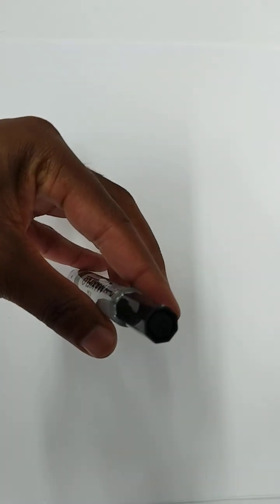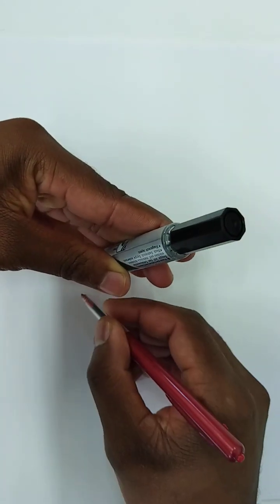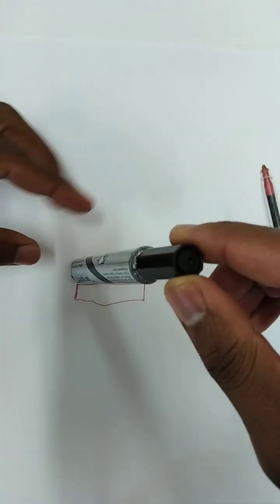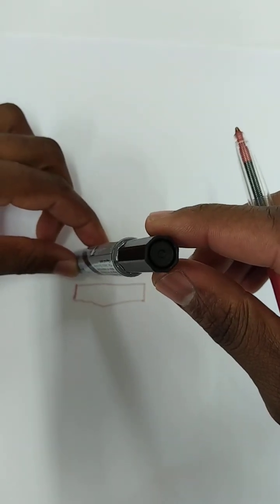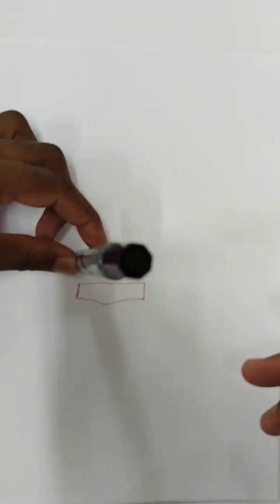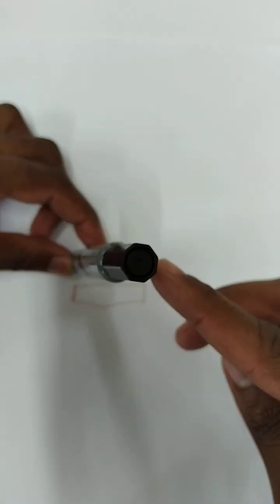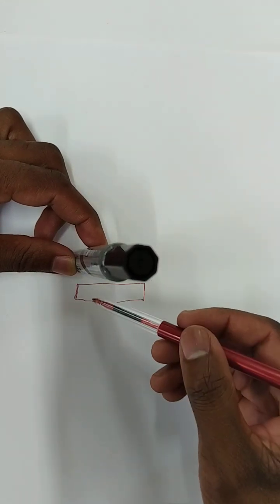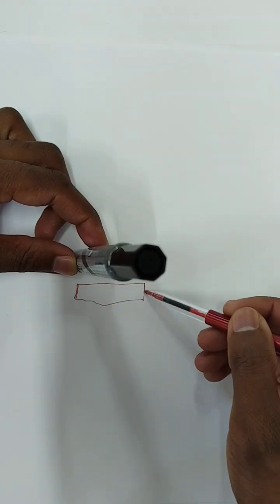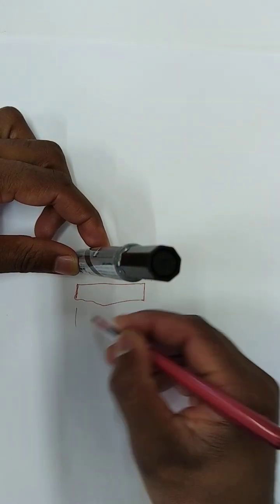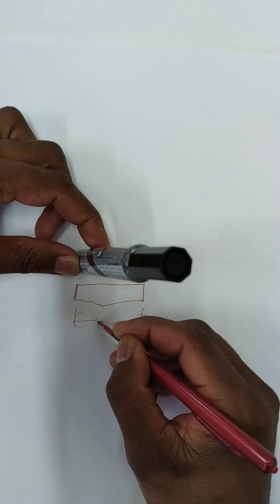You're going to draw something like this, starting from here up to there. So, which will represent the length of this marker when you look at it from the top. In other words, the length of this marker will appear to be shorter than in real. Therefore, we say that the length of this marker starts from here to there when we look at it from the top. But this length, we're going to call it untrue length.